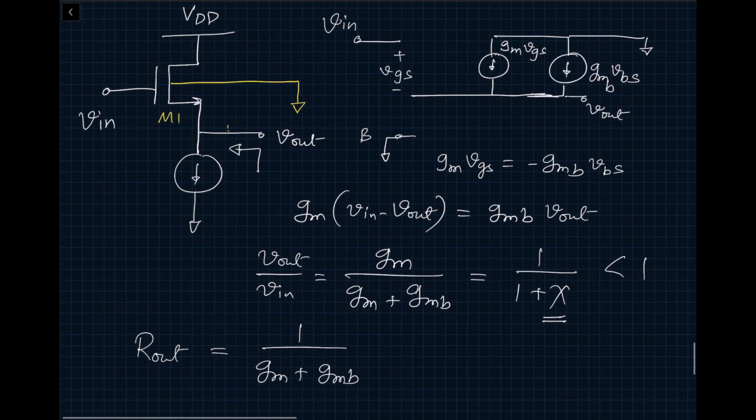So the rule of thumb again here is whenever you see a circuit where you don't define your backgate connection, then you have to do your first cut analysis without the body effect, and if it's an NMOS, then you have to look at the body effect and see its impact on your analysis. So body effect essentially complicates things slightly. So this kind of ends all the different configurations of bipolar transistors and MOSFET transistors or single transistor amplifiers. Now we will start building complex circuits where we have 2 or more transistors, and we will use all the insights that we have learned so far while we are building these new building blocks.